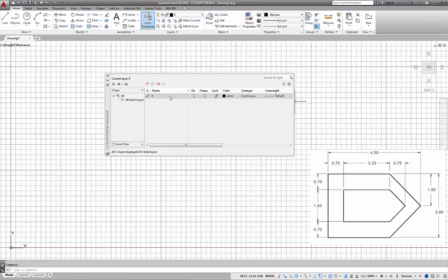And what that does is that helps us package our drawing into manageable bytes, meaning walls are on a layer, or object lines are on a layer, or our property lines are on a layer. And what that does is that allows me to categorize the items and control things like color and line type associated with those particular objects. Makes it easier to manage in the future also if I need to make changes. That's the idea.